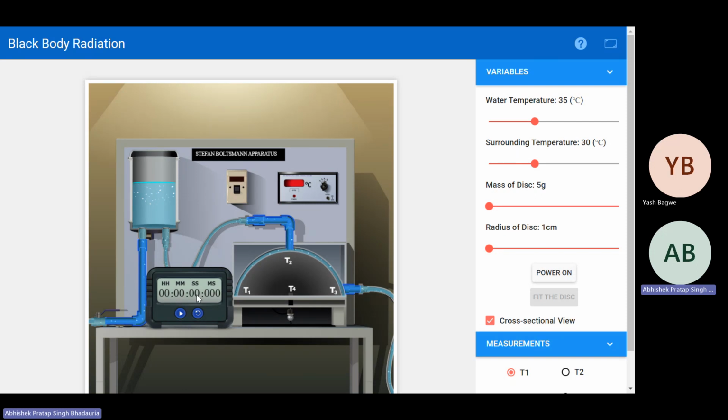The process will take place very fast, so my suggestion is, as per your convenience, you note down the temperature value for every 20 seconds, till we achieve the steady state. Tabulate those temperature values for the different time values. With these tabulated values, we will draw a graph of temperature versus time.